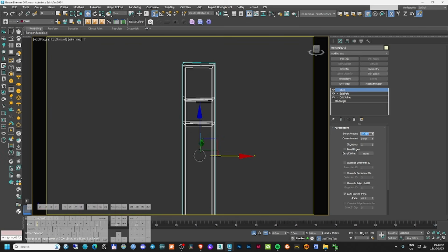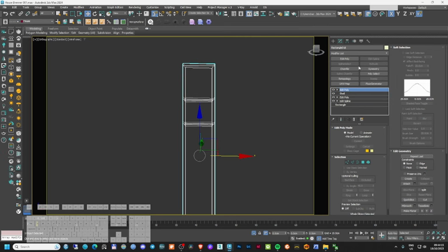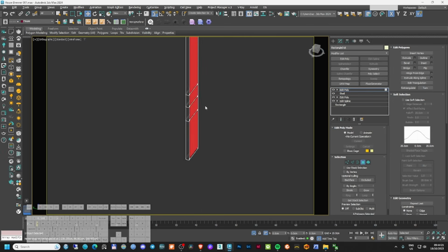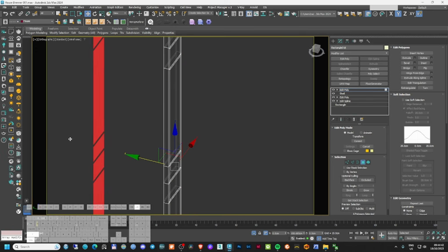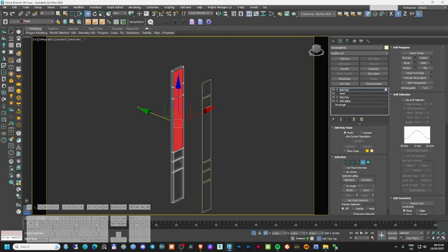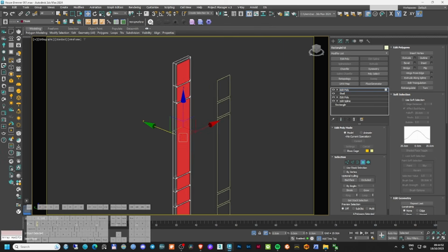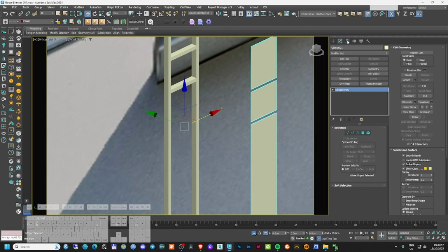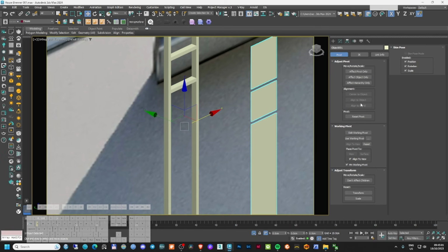Yeah, I could then 7, let's say. I'll create an editable poly, then I'll just select my windows. Make a copy of those polygons and then create a hole in here. So this can be the sheet of the glass.